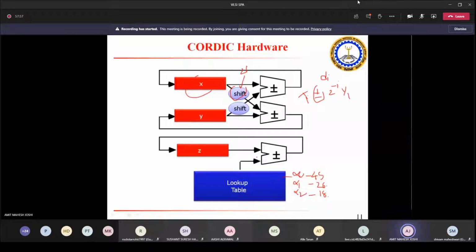So every time, whatever the z I am comparing with this. Initially I am starting with z equal to 0, and then I am comparing with 45. So initially I am considering that alpha 0 will be there, and then onwards whether it is a minus or plus alpha, this comparator will decide. If I compare 45 minus 30, the value is positive, so the next alpha is negative.